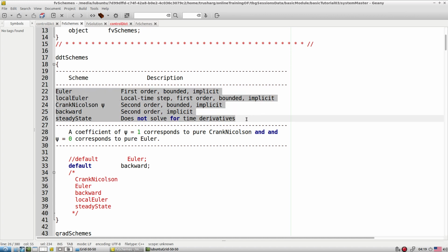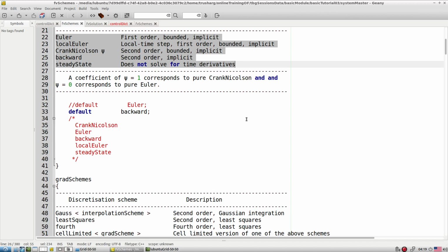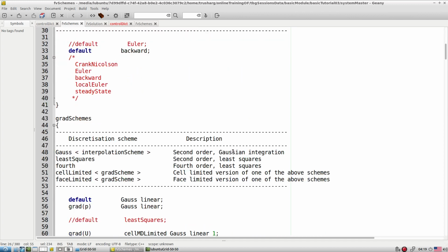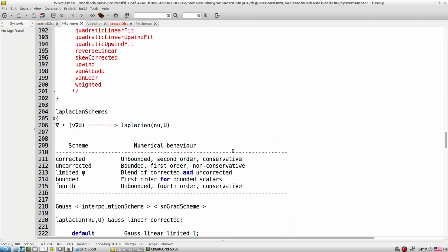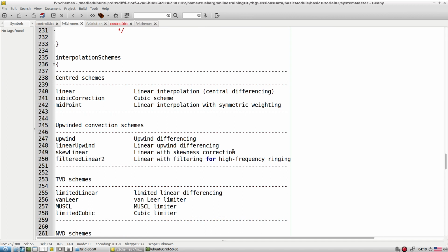Now after that we have an entry about gradient schemes. But before we move towards gradient schemes, a very important aspect required is the interpolations. So first we check that and then we come back to that part. Interpolation schemes normally allow us to interpolate the values from the cell center to the face center. For that we have a total of 4 categories available.